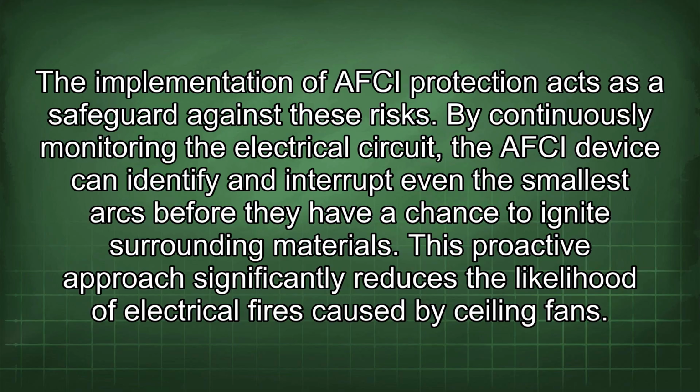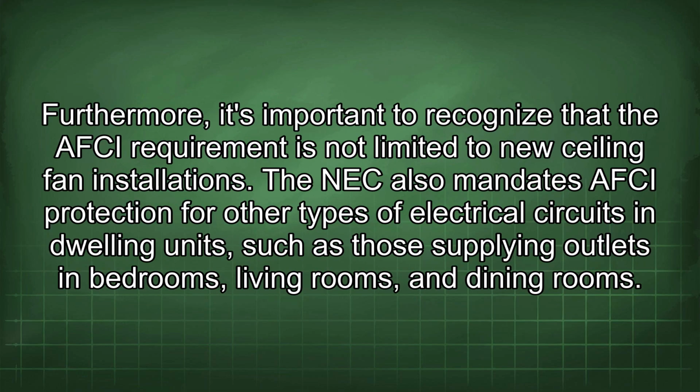This proactive approach significantly reduces the likelihood of electrical fires caused by ceiling fans. Furthermore, it's important to recognize that the AFCI requirement is not limited to new ceiling fan installations. The NEC also mandates AFCI protection for other types of electrical circuits in dwelling units, such as those supplying outlets in bedrooms, living rooms, and dining rooms.